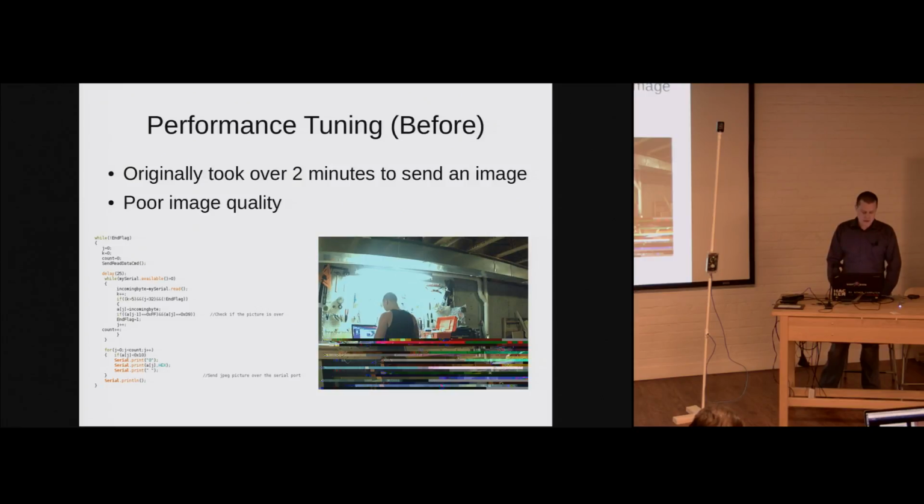And when I looked at this, I was using sample code that was provided with the actual camera. This was just C code, example Arduino code that they put out there to get you going. I found some issues with it. They were using a 25 millisecond delay in between iterations, which added time, obviously, to the total time it takes to process the image. And then they were using a buffer size of 32 bytes, which is one of the limitations on these boards. You don't have much internal memory.